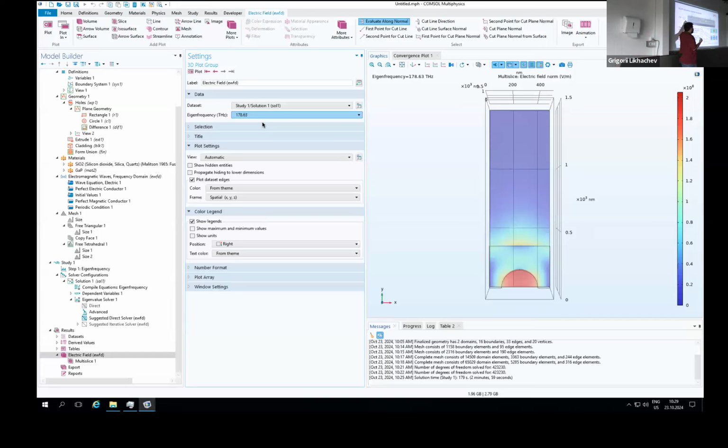So you make sure that higher frequencies are reflected first, so that the cavity length for these higher frequencies is shorter. If the cavity is shorter, the FSR will be larger. The lower frequencies propagate more inside the photonic crystal, so the effective cavity length for this frequency will be longer, which means the FSR is smaller.